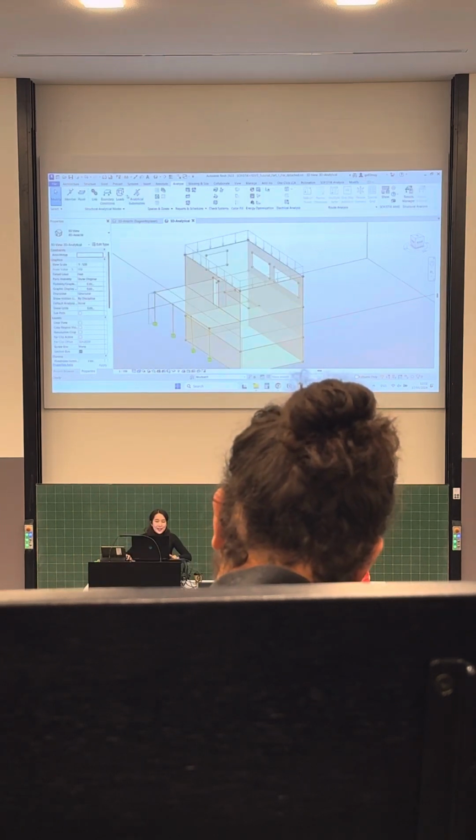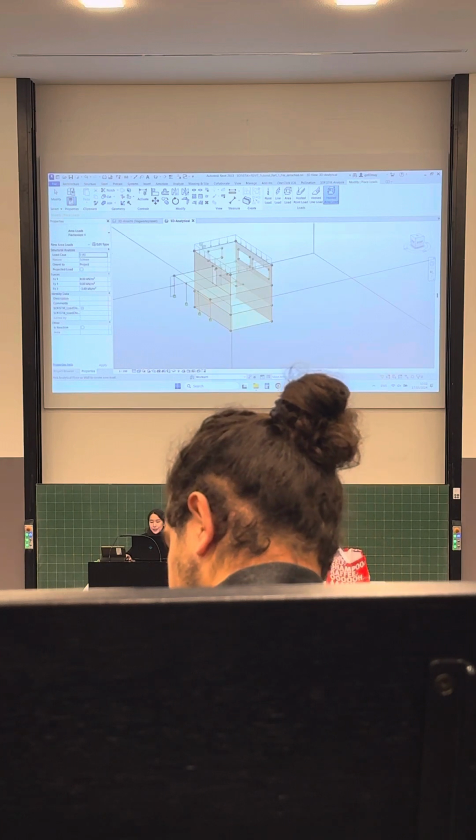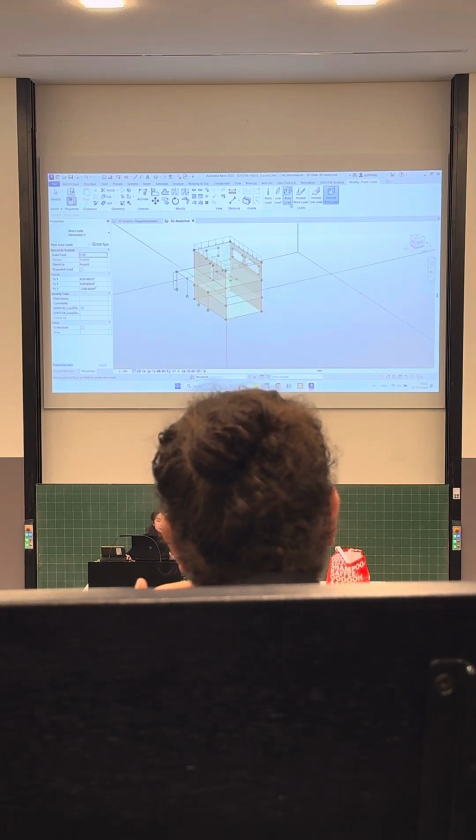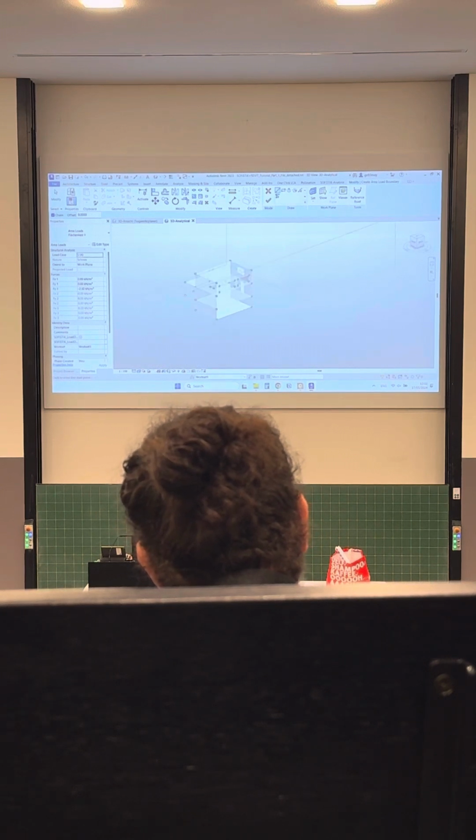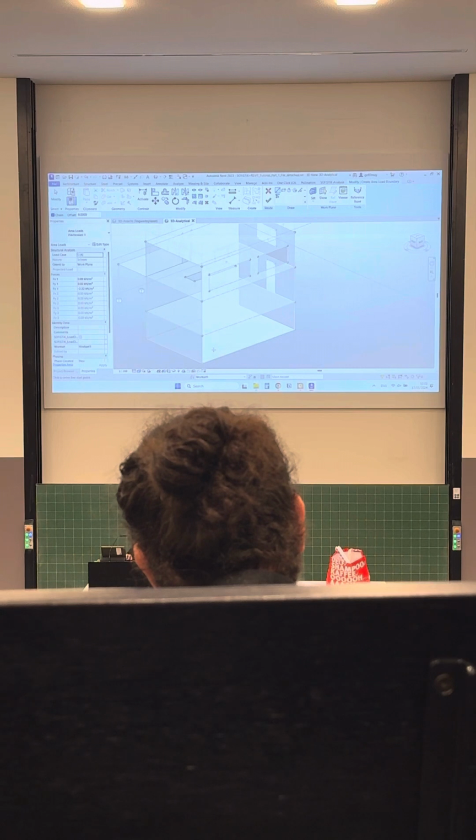Okay. You go into Analyze, Loads, and now we're going to try not hosted, but the area load itself. For example, you want it partially, not on the whole floor, but for example, I want it only on this half of the building. But yeah, doesn't matter. Let's try the area. Let's set the work plane, because now, for example, I cannot draw on this side, and I want to draw on this panel, and I cannot. So you have to set the work plane. And there are two different ways to set it.